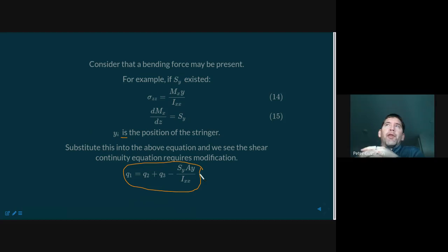Now, I still have to be cautious because we did make a number of assumptions along the way. For example, the length of the beam is much longer than any length in its characteristic cross section. We talked about thin-walled sections. We talked about many assumptions, geometric and material, along the way. That may not always be true, and so there are some more advanced beam theories that can be examined when those assumptions are not as precise as we'd like them to be. But that will be covered in other courses if you continue on for a graduate degree in structural mechanics, aerospace engineering here at WMU or elsewhere.